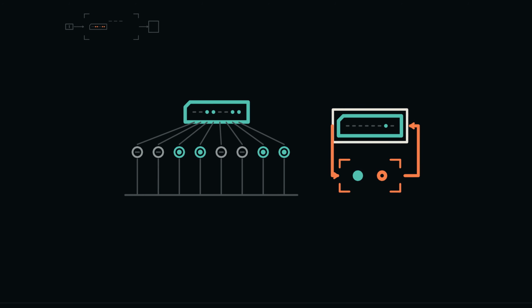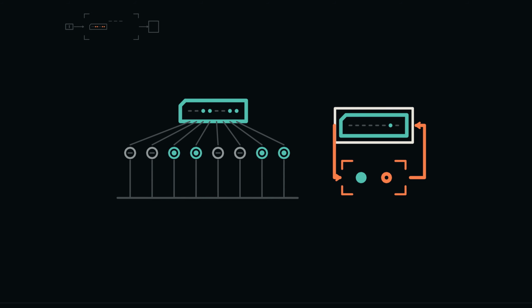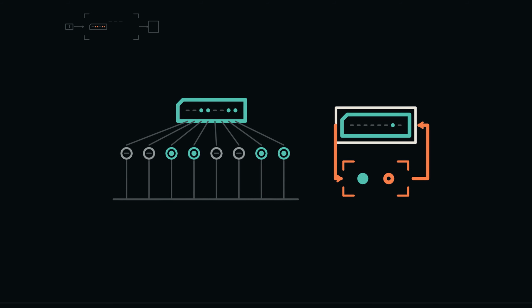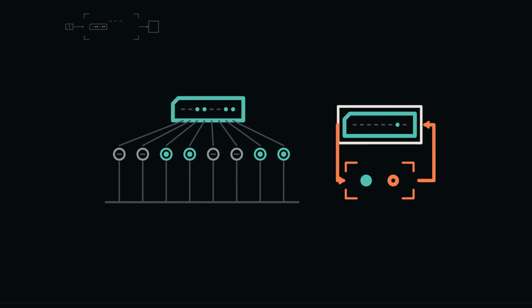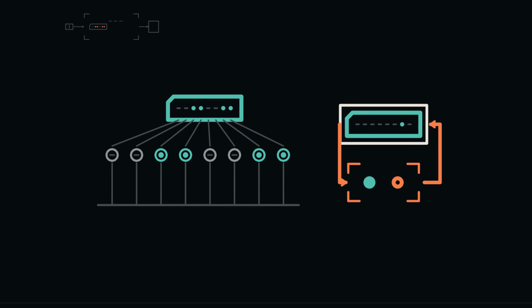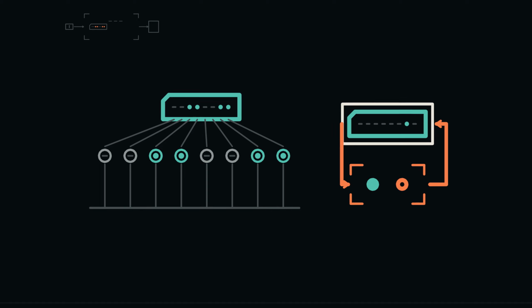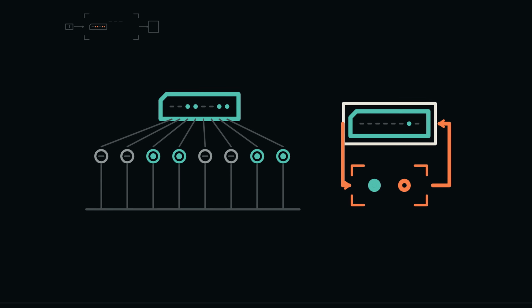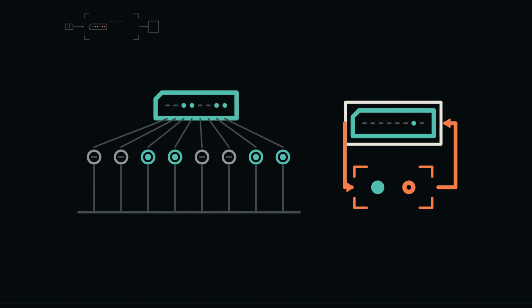The current low 4 positions are 0, 1, 1, 1. Predict the next enabled state using the rule: change trailing ones to 0, then change the first 0 on their left to 1. The result is 1, 0, 0, 0. If enable is 0 at the edge, the selector returns the old pattern instead, and no count is committed. The incremented proposal may still exist inside the combinational network, but only the selected value crosses the storage boundary.